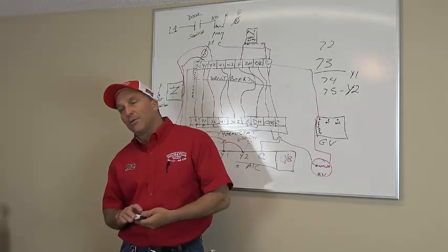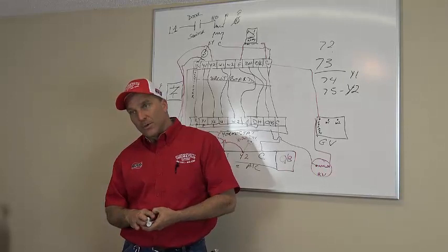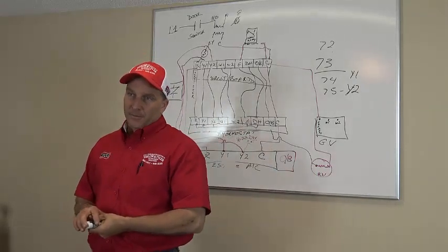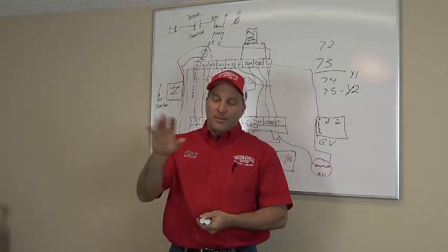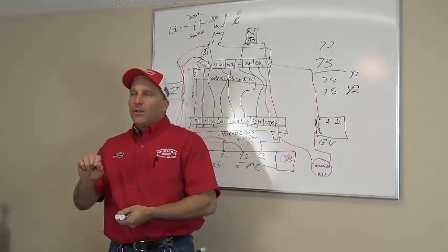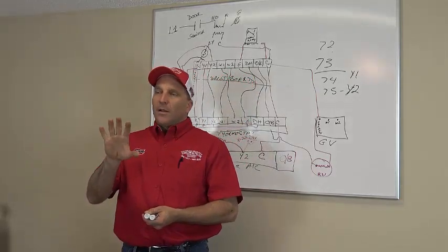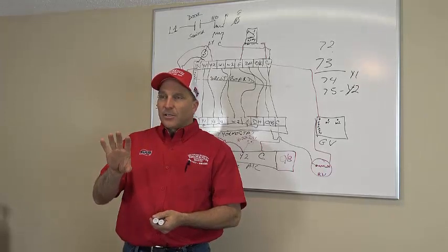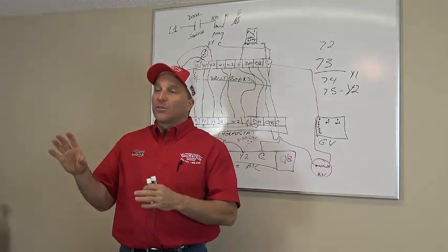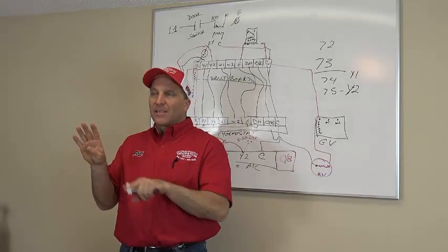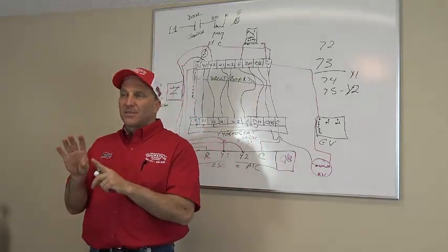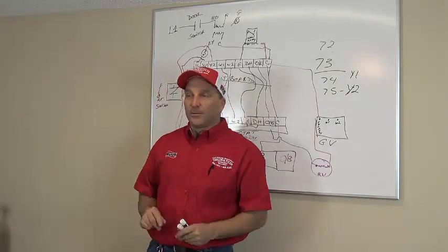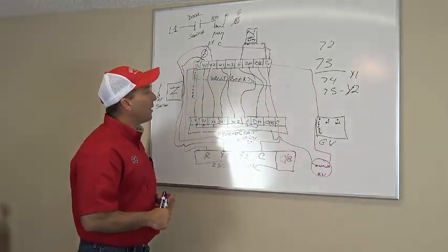70% of your setting for your cool. Okay? So if I got a 100,000 BTU system, okay? I'm sorry. Let me back up. I said it wrong. You're going to run 100% capacity in second stage. If you have, let's call it 1,000 CFMs in second stage, you're going to run 70% of that 1,000 CFM setting for second stage. Not cool. Second stage heat. Okay? I said it wrong. All right?